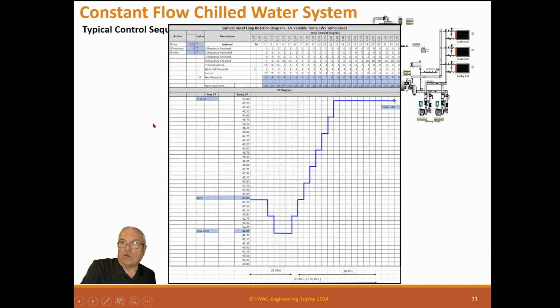And then this is the chart I use to tell how fast and slow the determination time is. So for this one, if you have 44 degrees and it comes out to a 6-minute wait time and 3-minute measure time, if it's getting reset requests past the ignores, it drops 1, waits 3 more minutes, it's got more, it drops down. Now it's at minimum temperature, 42, and it stays there until it gets an increase, and now it starts increasing. Now this again was faked out up here, so I could tell what the maximum speed was, these could actually change.